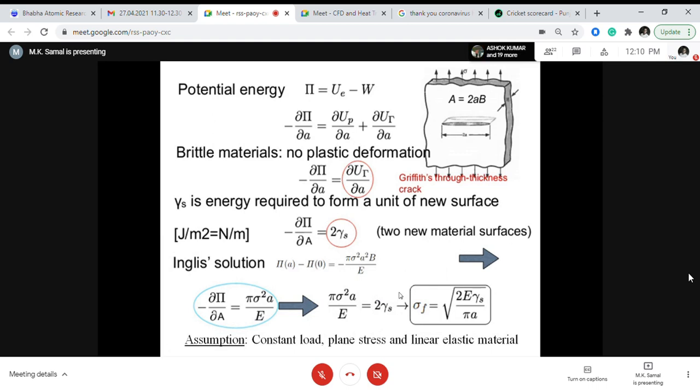Then, if you apply the concept of LEFM, that is the stress intensity factor K1, then it will not be very far off. It will still be close to the exact solution, or close to the actual situation. So LEFM tries to take advantage of the situation where plasticity is very small, that is, a limited plastic deformation in the material. So, we will be talking about those cases.